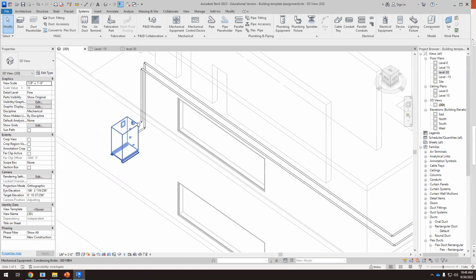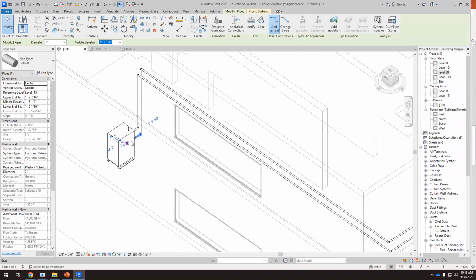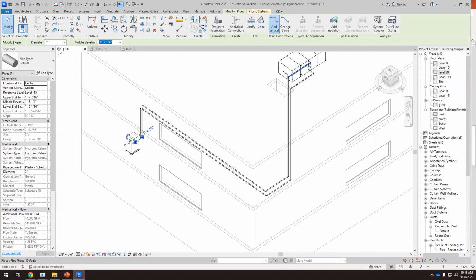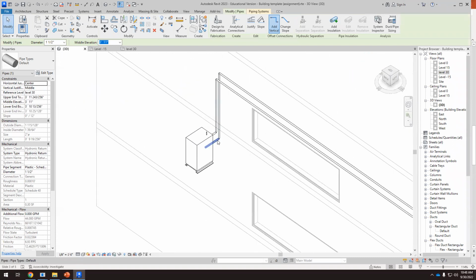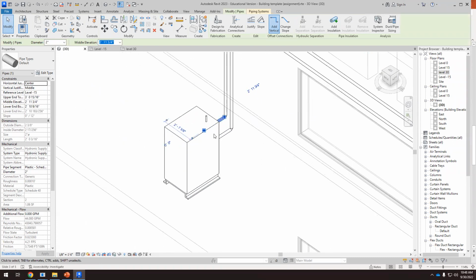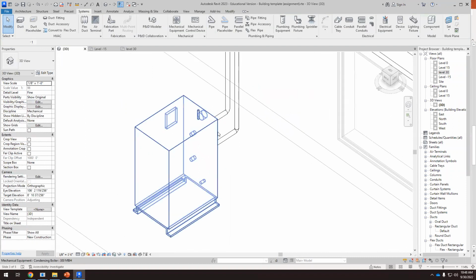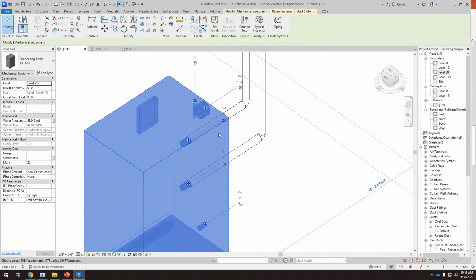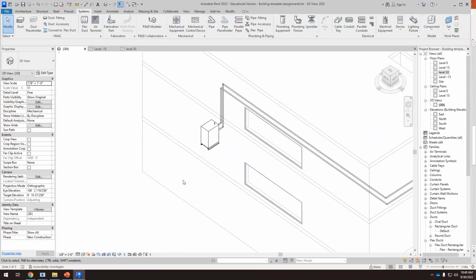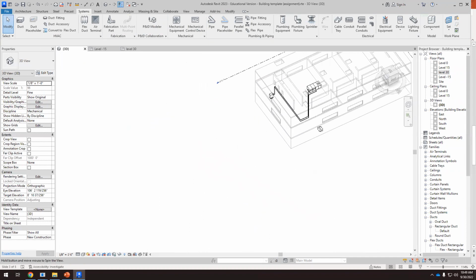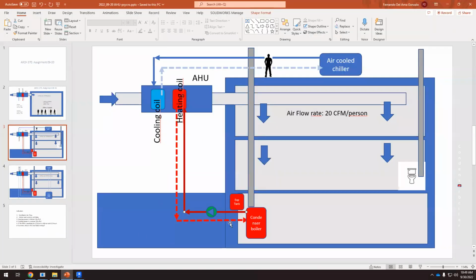We have the same, the first circuit. This is connected to this, and then the outlet of the heating coil is connected to the inlet of the boiler. Well, outlet, inlet, inlet. So they are both correct. So in this schematic view, we have done the red ones. Okay, so we have connected the condenser boiler to the heating coil to the supply and the return.